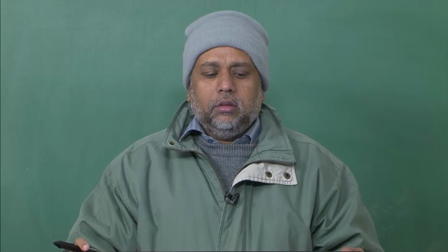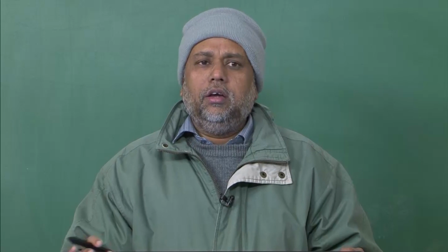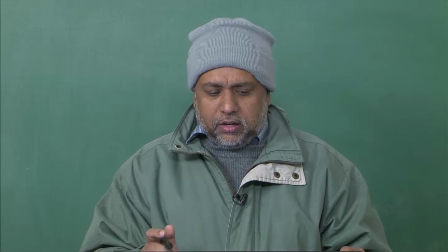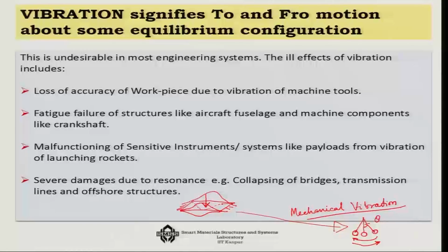Now, this vibration is undesirable in all engineering systems, because as you can see in this particular plate case, the plate is vibrating back and forth and back and forth, and consider that the plate is a part of an aircraft fuselage. So, what will happen is that something like a fatigue failure will happen to the system.